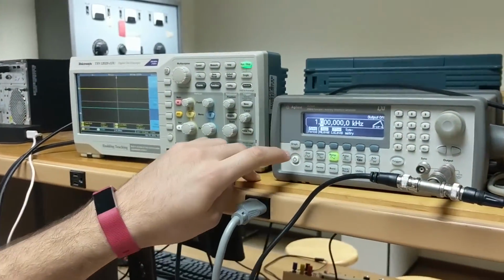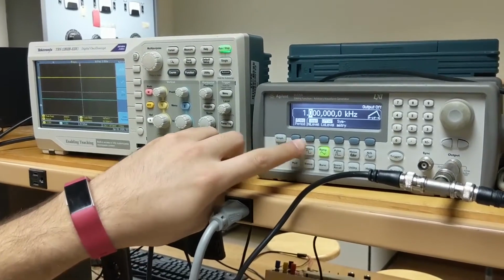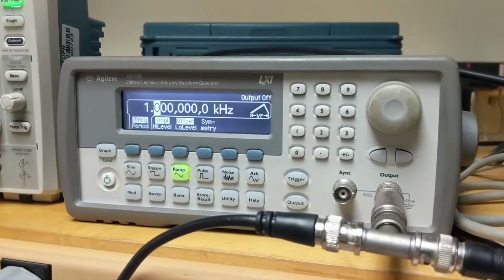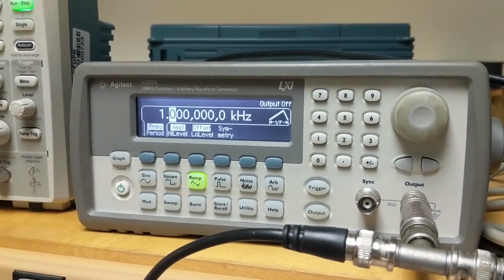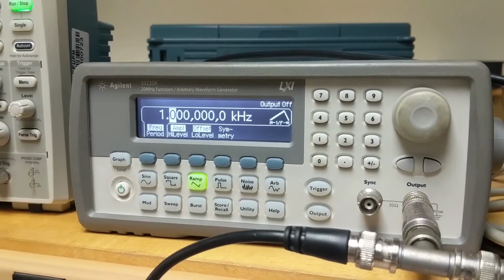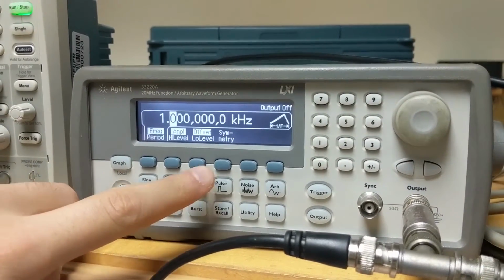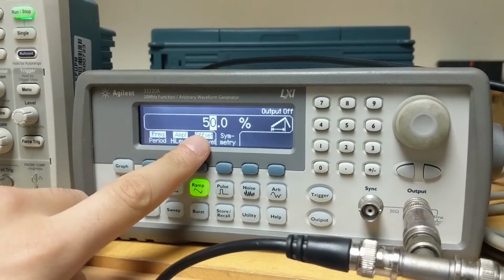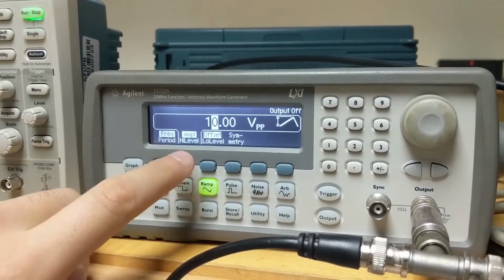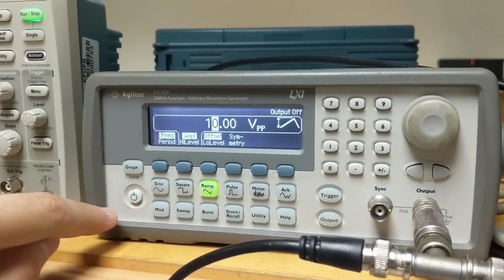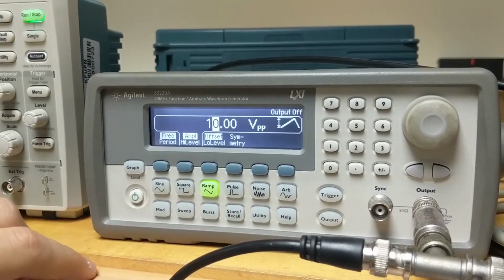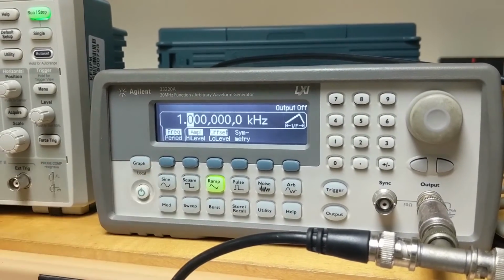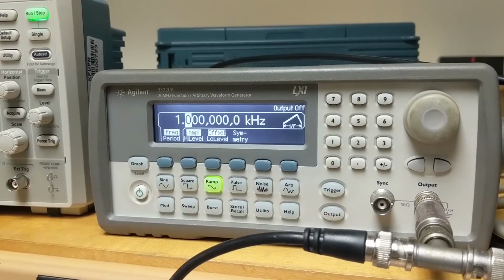If we apply the DC supply, we'll define our input to be a triangular wave. Our input will be a triangular wave of frequency 1 kHz. To define a triangular wave in our function generator, we'll select the ramp and set the symmetry to be 50%. The amplitude will be 10 volts peak to peak, so the maximum will be 5 volts and the minimum will be minus 5 volts. And the frequency, as we said, will be 1 kHz.